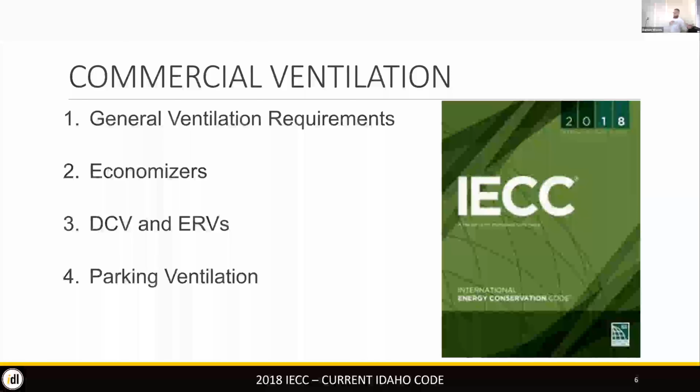But from an energy standpoint, the more air you bring into the building, the more energy it takes to heat up or cool it down. So there's that tension. And so from the energy code, it's not necessarily about pulling back on the fresh air. It's more having the ability to pull back on the fresh air. A lot of it is about controls.